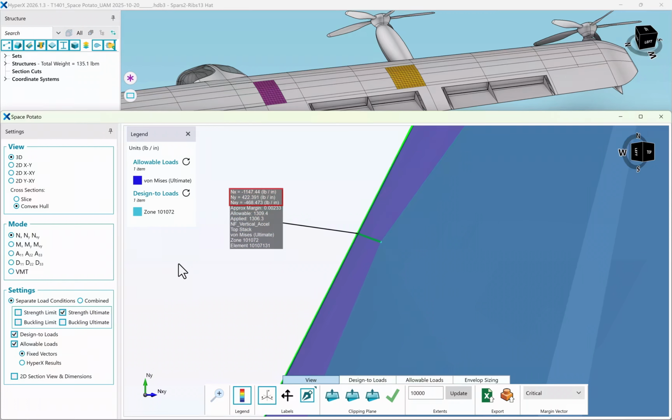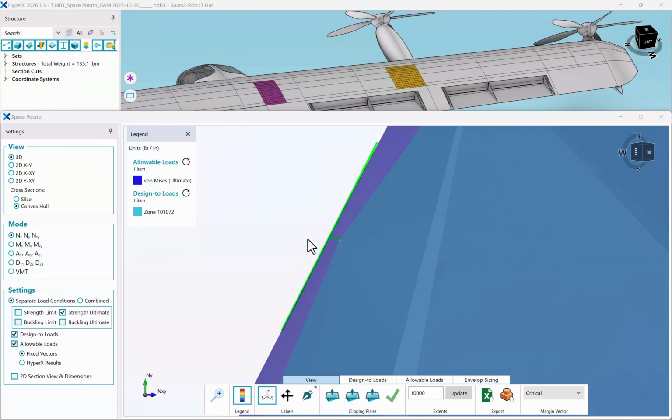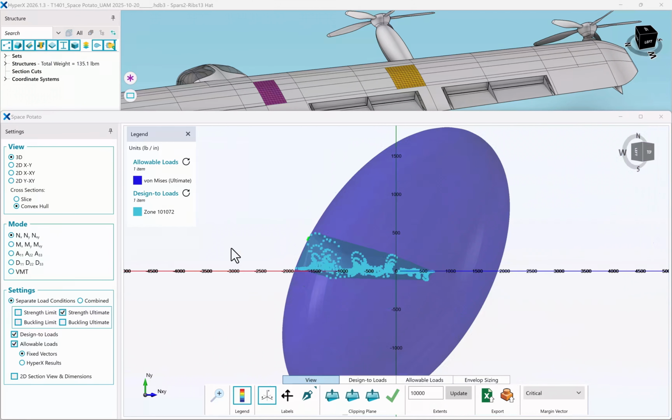In this case, though, the panel was more dominated by interaction of load components, which is better captured in 3D. Point being, in many cases, the critical load surface and analysis failure surface is not able to be seen in any of the 2D envelopes, as it is truly a combination of all three load components.